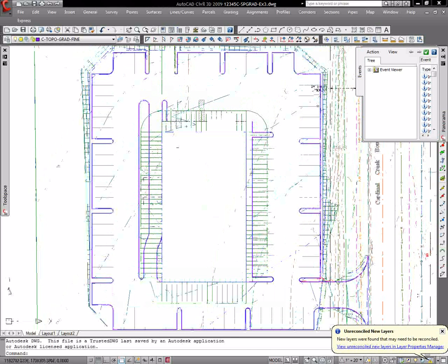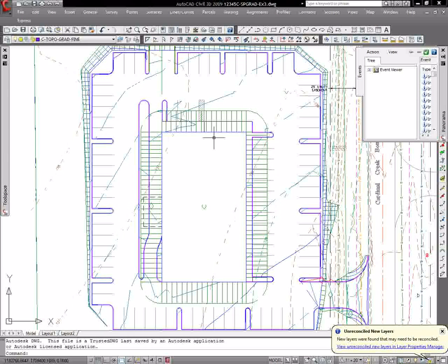Also, the north face of the building, which is the front, is where the main entrance is, and the client would like to see at-grade pedestrian access across the entire front of the building. So basically we want to eliminate any curb right here, and we also need the grades to be at finished grade across the front of the building, and currently they are sloping to the south and east, so as one travels across the face of the building, they are traveling downhill the way the grades are right now. So we need to address those situations and get the grades where they need to be for this particular design.